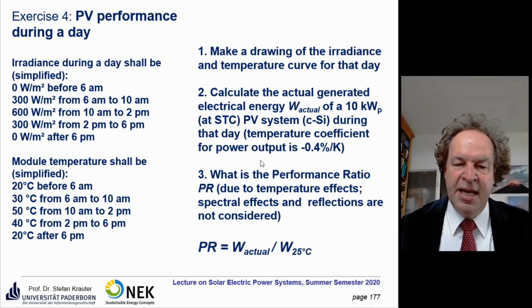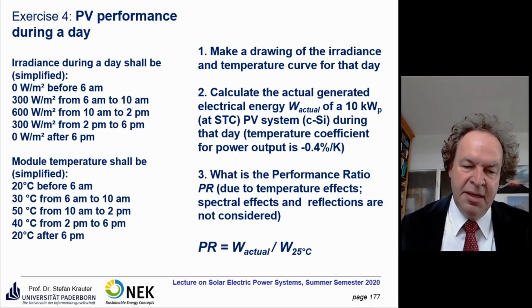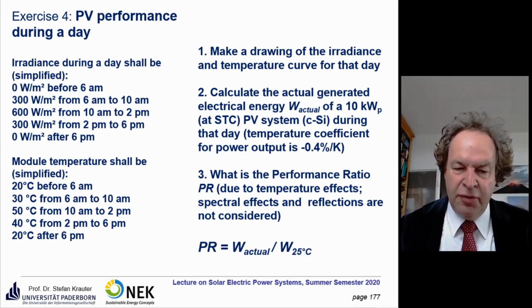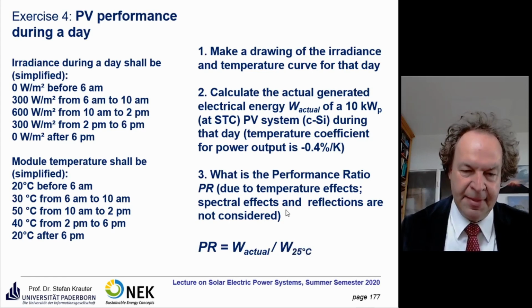And then you are asked about the performance ratio. This is the relation of the electricity actually generated in relation to what would be generated, given the irradiance, at 25 degrees cell temperature, such as STC conditions.